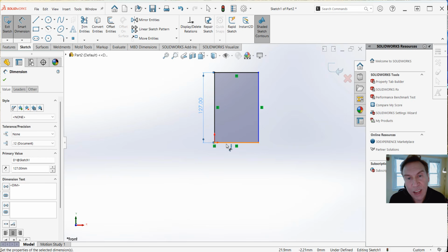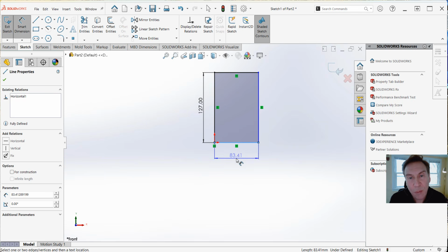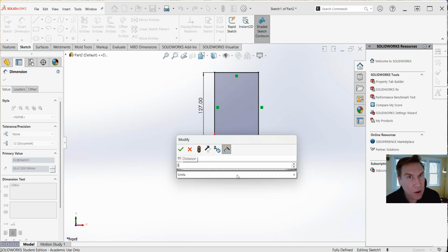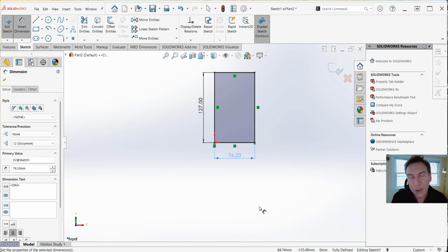But now hover over this line down here and click. Move it to the center down below and click. Again, stay away from points. Click. And now this needs to be 3. And does anyone remember, if we wanted it in inches, what are the 2 things we could do? There's actually more than just 2 things you could do, but I'm just showing you 2 for right now. Okay, you could type in IN, or I said you could type in the quote. Either one is fine, and you could hit enter or the green check. It will give you the metric equivalent.